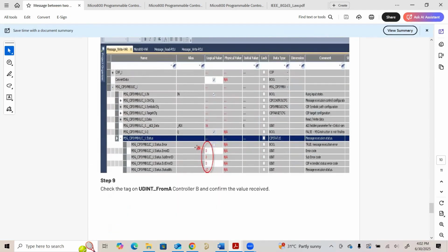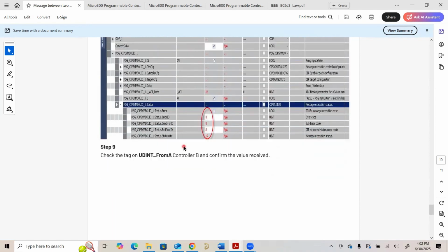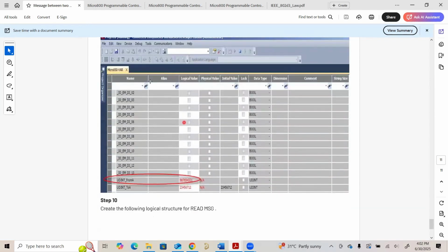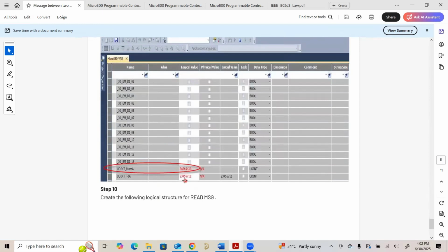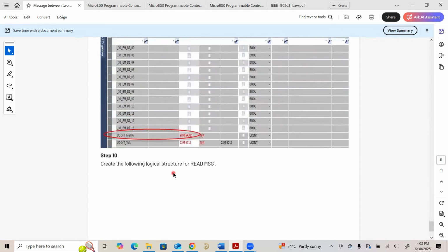So when you send in the data, your PLC A should look like that. This is PLC-B. In your global variable list, you should see the data coming from PLC-A. For light indicators, you can create an additional ladder diagram for comparing the number of vehicles, and based on the received value, this global variable, you can compare it and control the indicating lamps.